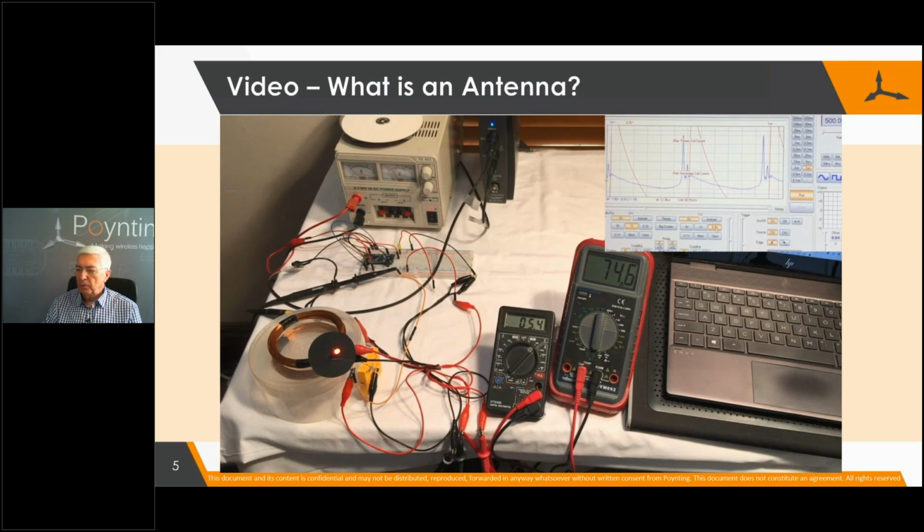Right, so what I'm going to do next is I'm going to show you what happens when a router that has an inbuilt antenna is located inside a building, and you'll see me there picking up just some normal DVDs. Now, as you know, these DVDs have an aluminum surface that is the recording surface. Now that surface, you can see, tends to attenuate the electromagnetic wave, or the magnetic wave in this instance, the near field.